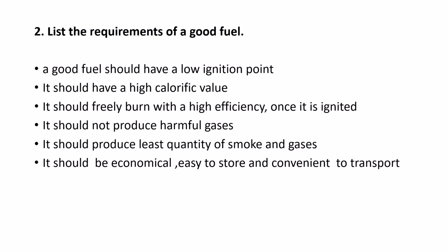Second question, list the requirements of good fuel. A good fuel should have a low ignition point. It should have a high calorific value. It should freely burn with a high efficiency once it is ignited. It should not produce harmful gases. It should produce least quantity of smoke and gases. It should be economical, easy to store, and convenient to transport.